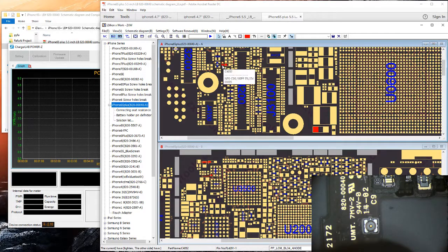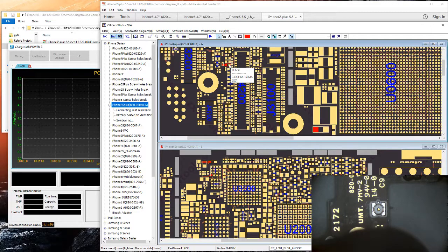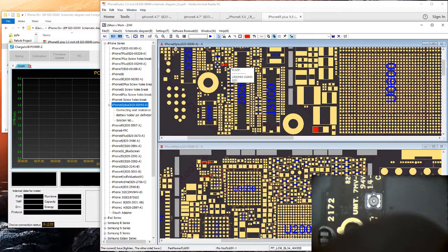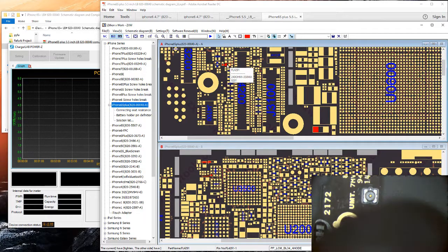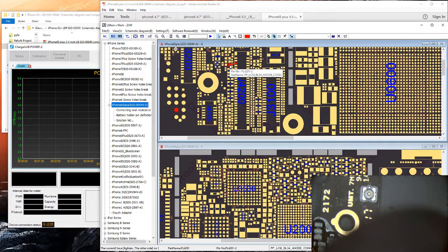This side of the filter has another little cap on it and it goes back here. The way it's physically laid out under the board, if this filter gets blown, it usually melts so bad that instead of being soldered to the pad, the metal contacts are actually welded to the pad. So when it comes up, it likes to rip that pad out. There's a three-way junction under here.